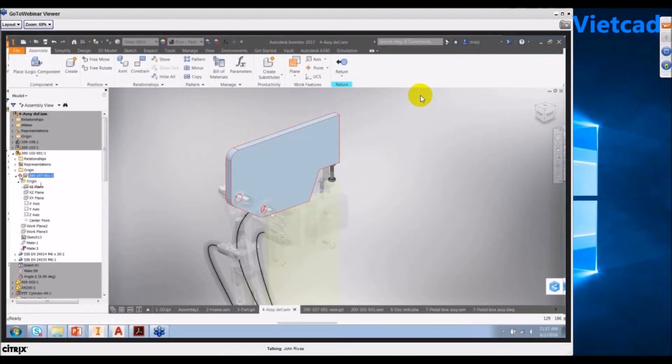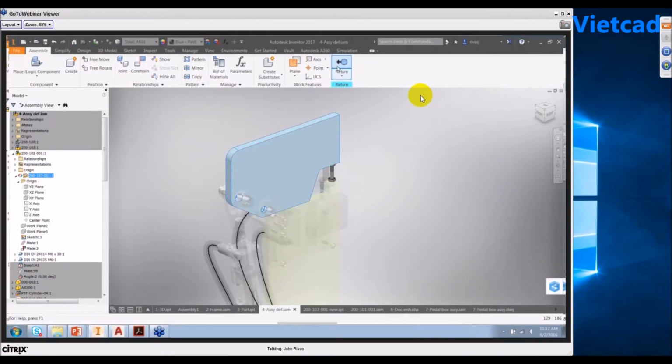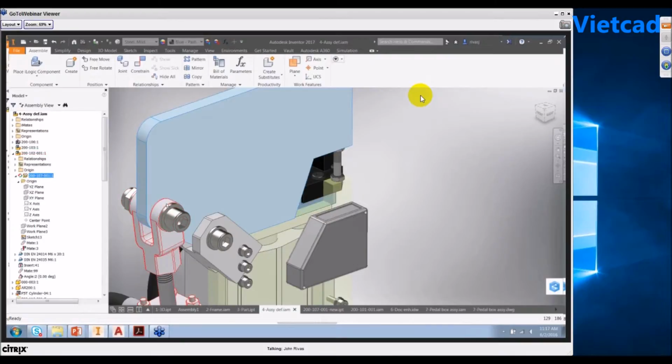So now within Inventor 2017, once you see this adaptive feature, you can open up the references of this part. So it's part of the new capabilities that we have inside 2017. So if it is referenced to another component, based on the reference sketch, it will open up that part. Let's say if it is referenced on this particular bolt, it will automatically open up within Inventor.